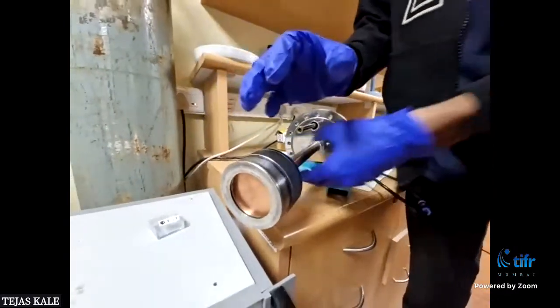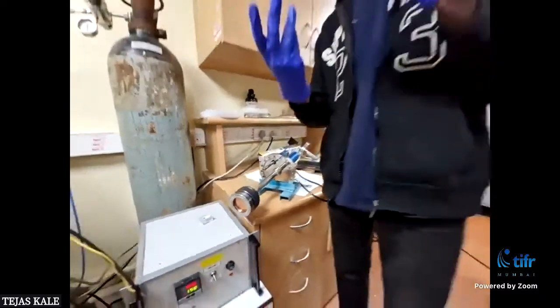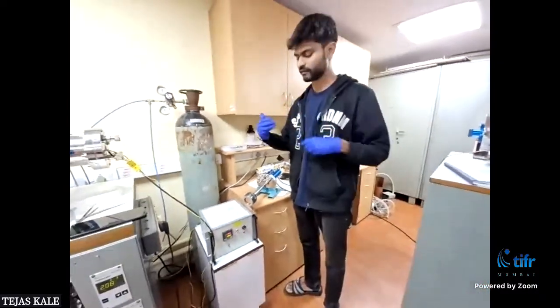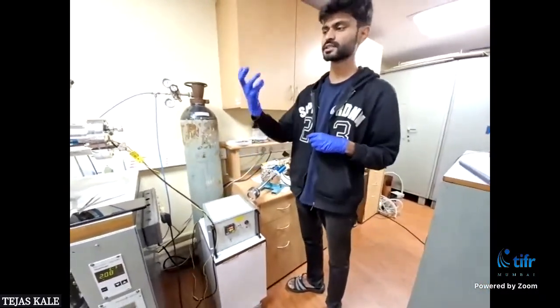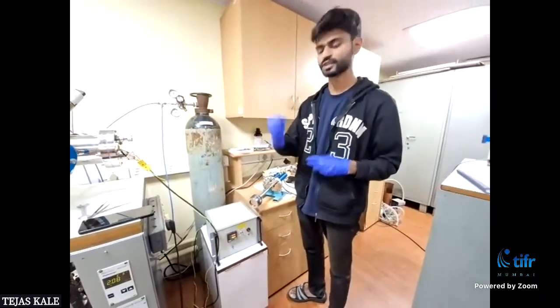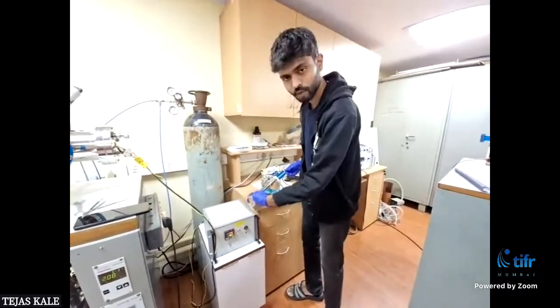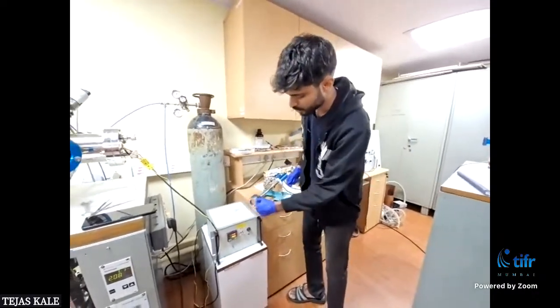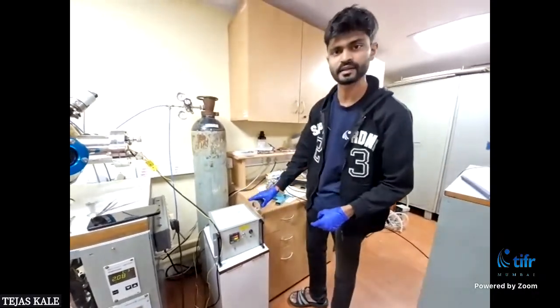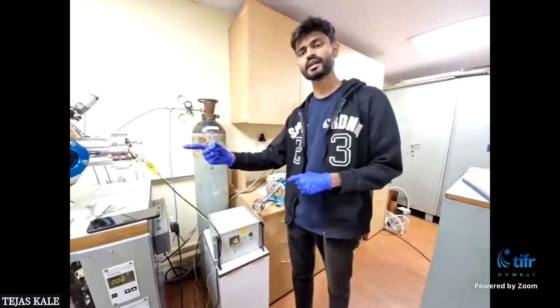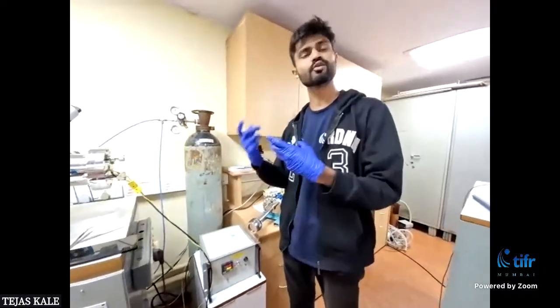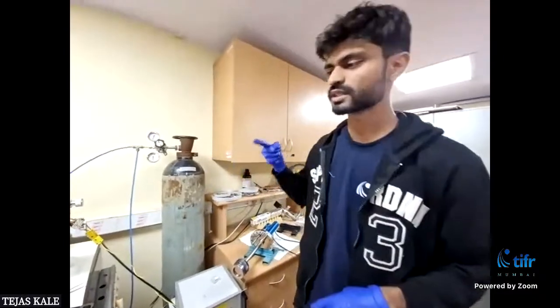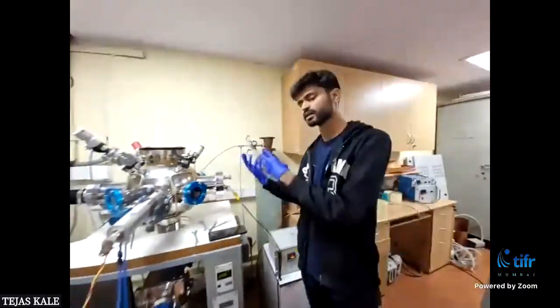And these electrons will collide with the argon atoms, creating argon ions because of the movement of electrons away from this target material. These argon ions are positively charged, and they come towards this copper target. Through the collisions, they knock out copper particles from this target material, which go straight away because of the large mean free path we create with these vacuum conditions. They go straight and deposit on the sapphire substrate.